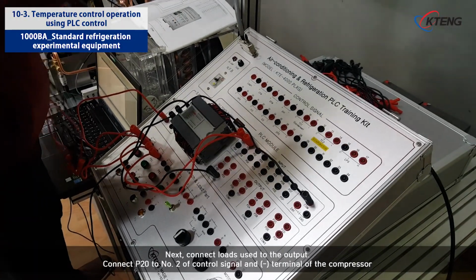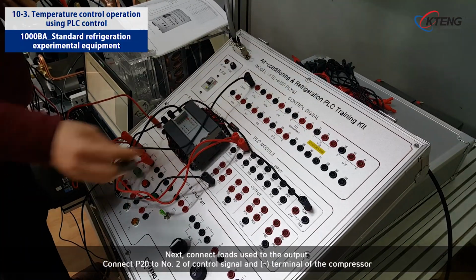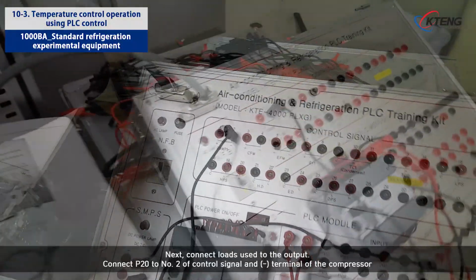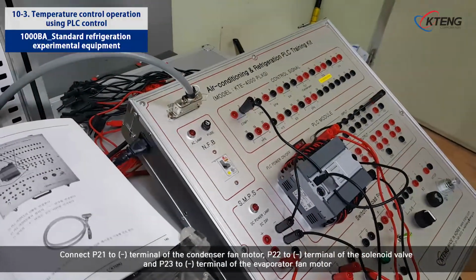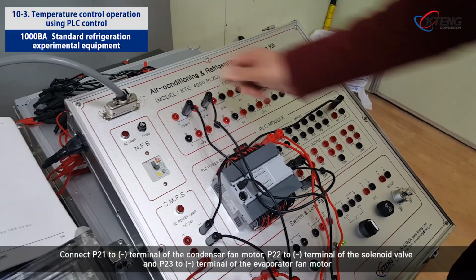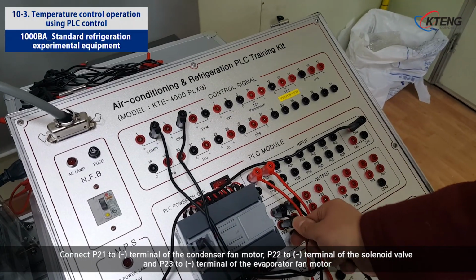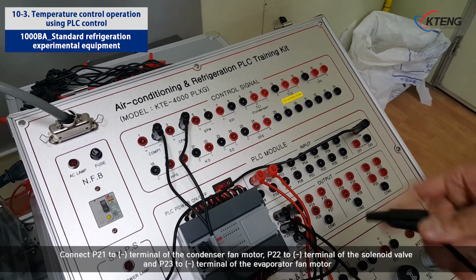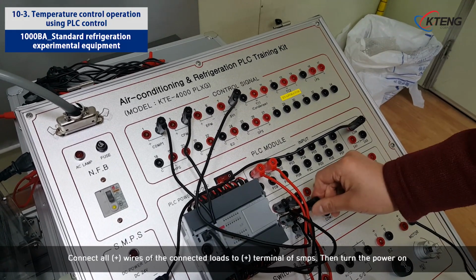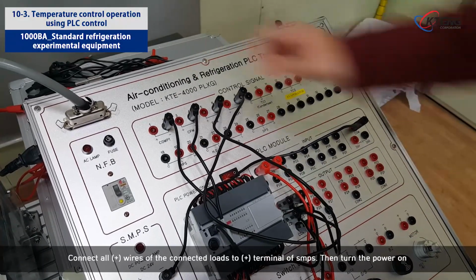Next, connect loads used to the output. Connect P20 to number 2 of control signal and the negative terminal of the compressor. Connect P21 to negative terminal of the condenser fan motor, P22 to negative terminal of the solenoid valve, and P23 to negative terminal of the evaporator fan motor. Connect all positive wires of the connected loads to positive terminals of SMPS. Then turn the power on.